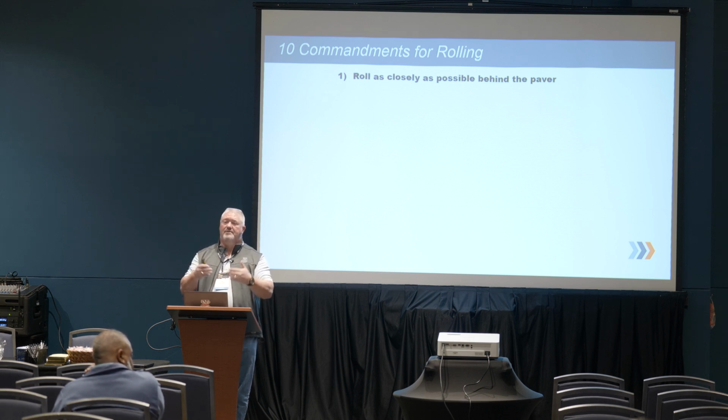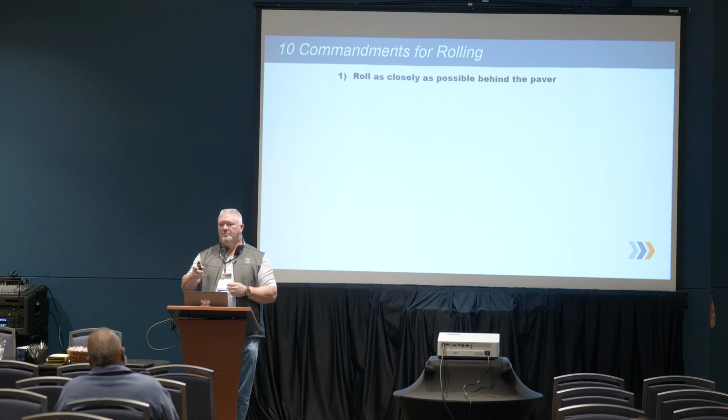Now, if the paver stops and you want to get compaction up to the screed, that's a different thing. But as long as that paver is moving, I don't need to get that close. I want to be consistent with my passes.